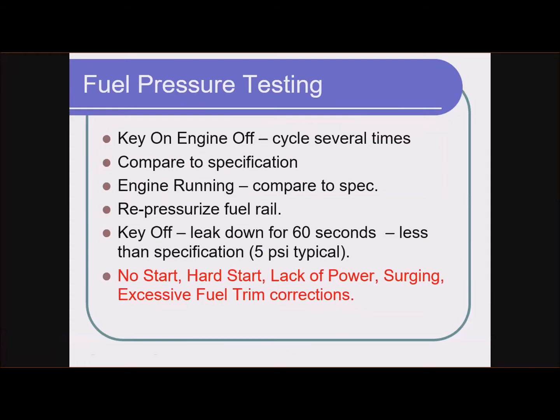Let's skip over hard start for a minute. Lack of power. If your fuel pressure is low, enough to start the vehicle, but not enough to supply sufficient pressure for conditions where a lot of power is needed, that could be a fuel pressure issue.